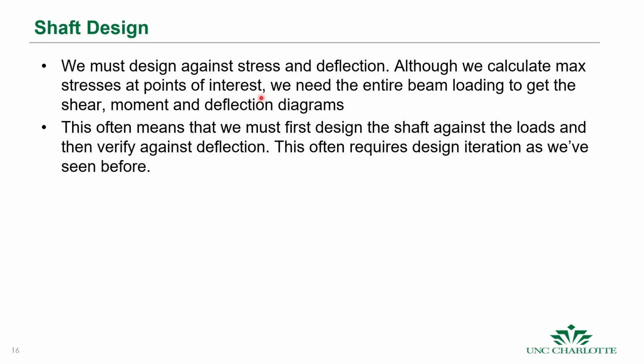And obviously to calculate that, we have to have the loading functions for the beam for the shear and moment and deflection diagrams. So just like before, when we're doing real design, we often have to do the design against the loads and then investigate the deflection, and if the deflection is too large or the loads are too large, then we have to iterate in the design, which usually effectively comes down to just selecting a larger diameter material.